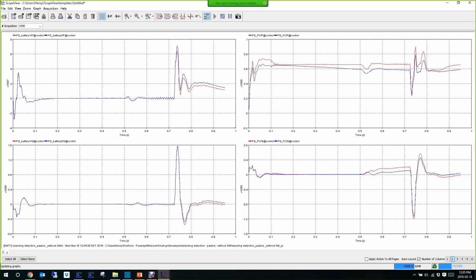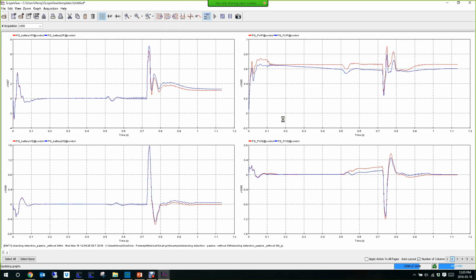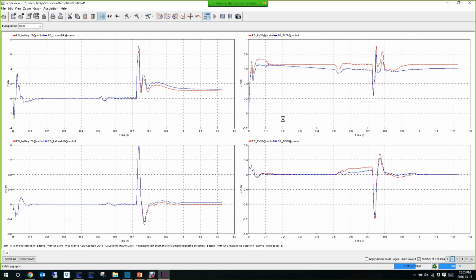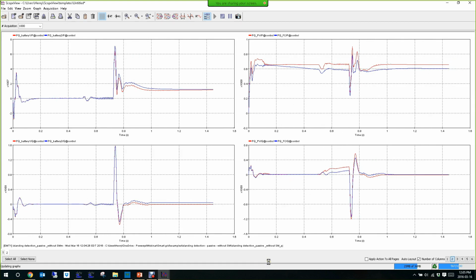We can actually already see the difference in the reactive power. Before one was positive, one was negative. But as you see now, they converge to the same value. So that's very good, okay? Because now we both produce the same, and we don't have the circulating reactive power anymore. It doesn't match exactly, but it's still way better. Okay, so that's a very important point. The droop control when you have several DGs in the same microgrid.